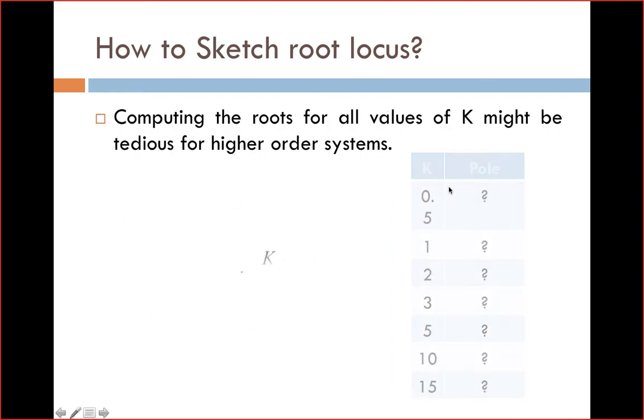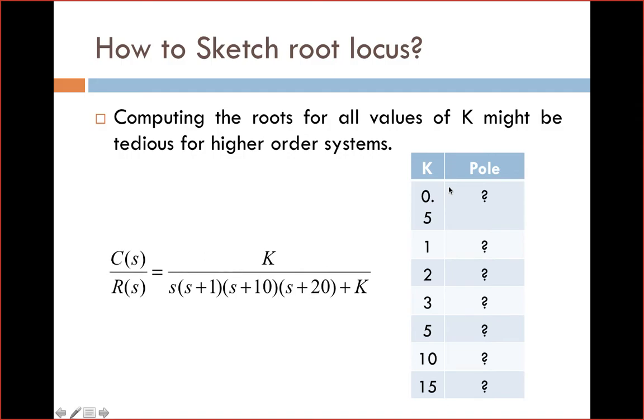But if you come across this kind of equation, first, by seeing this, I can say that the order of the characteristic equation is 1, 2, 3, 4. A fourth order characteristic equation is very difficult to find out the value of poles on the S plane, because it may have four different poles. You have to identify four different poles on the S plane.